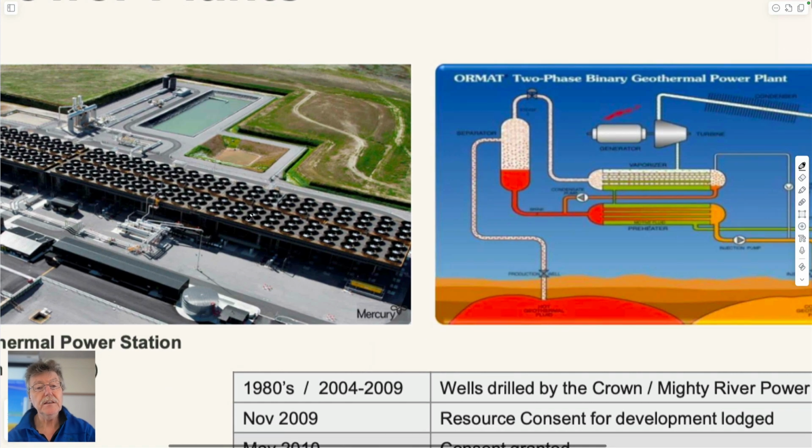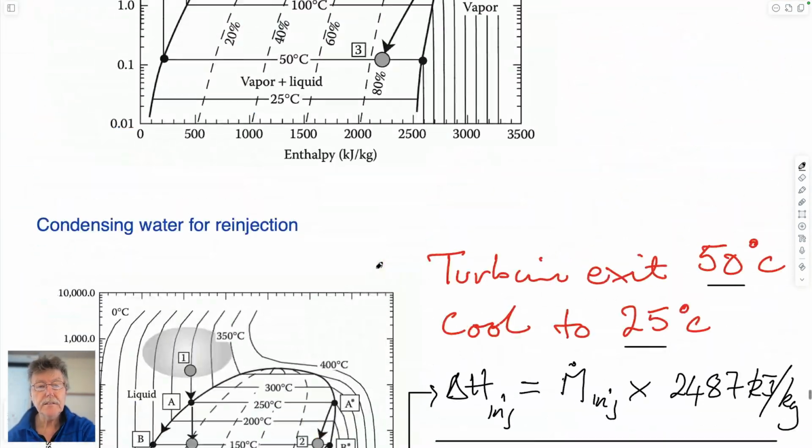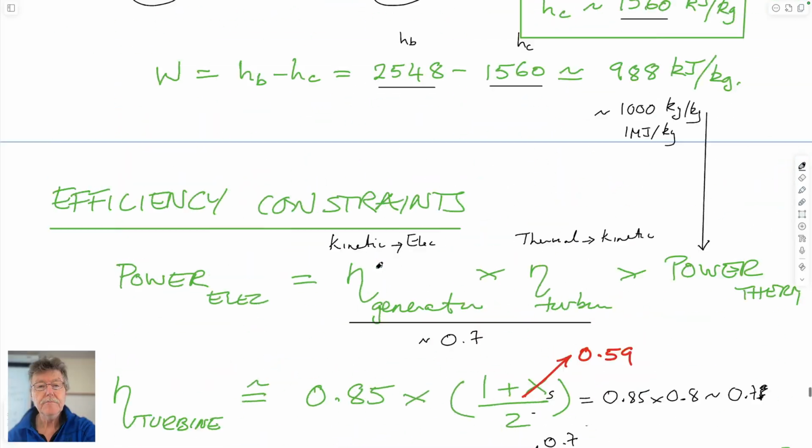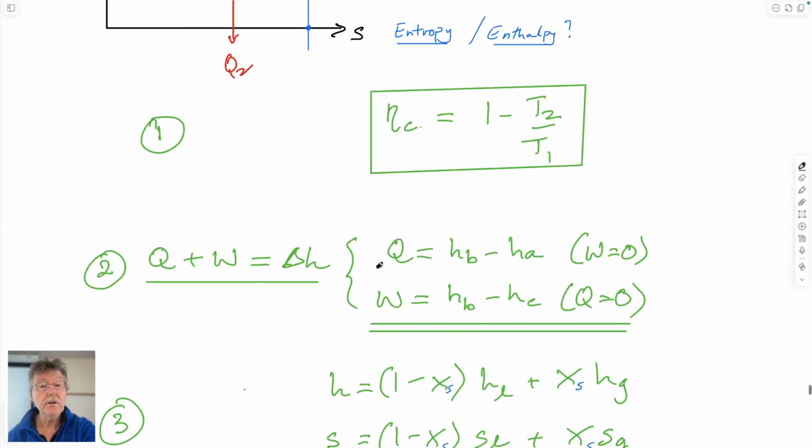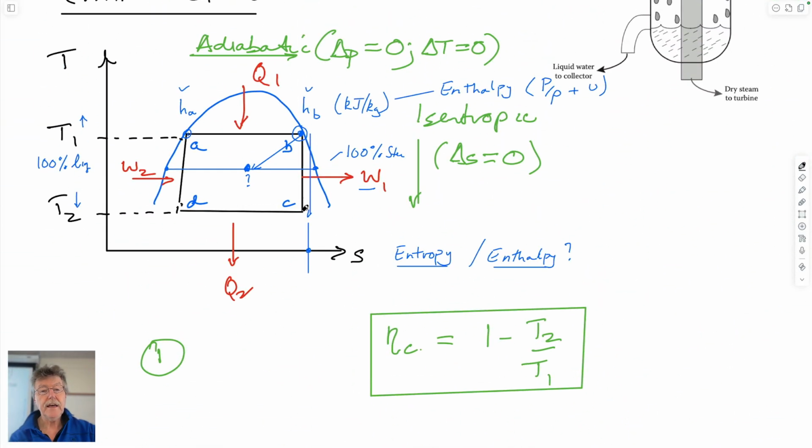So sometimes when you see these cooling towers, the liquid that's running around in these is isopentane, which is being cooled by the ambient temperature at 20 degrees centigrade or 30 degrees centigrade by air, and then cooled and recompressed and then pumped underground. And so in those particular cases, what that is following is this lower limb on the Carnot cycle. So it's coming in as vapor, it's being cooled by the air temperature that's adjacent to the radiators.